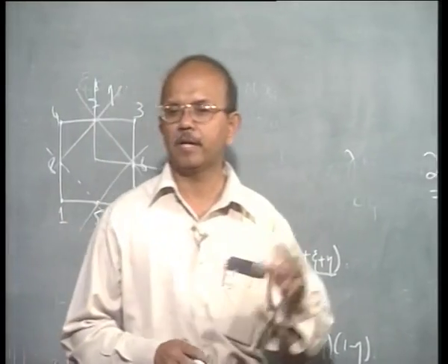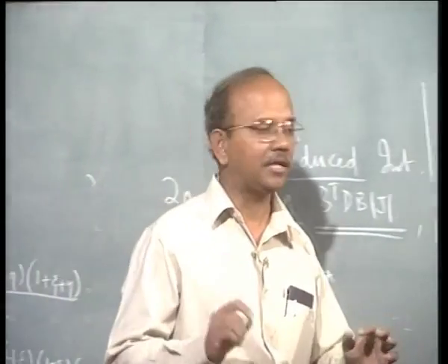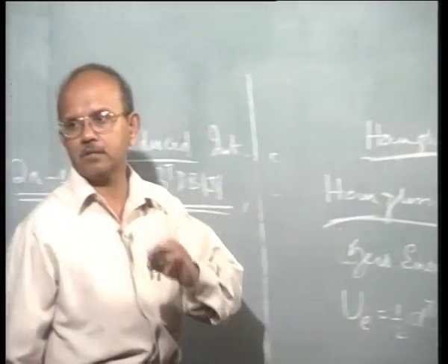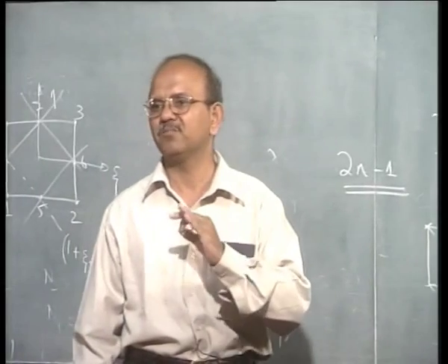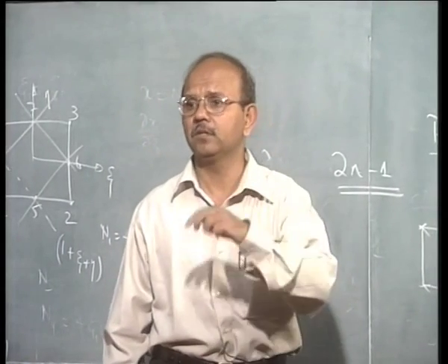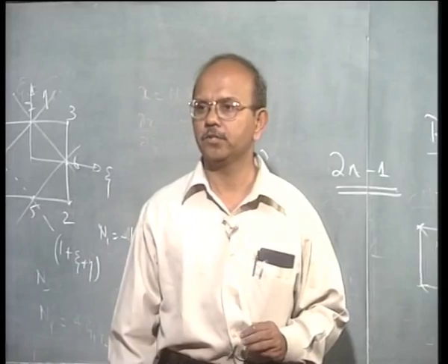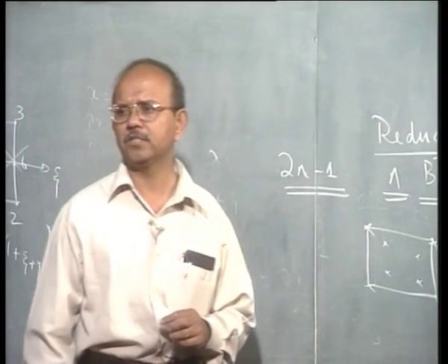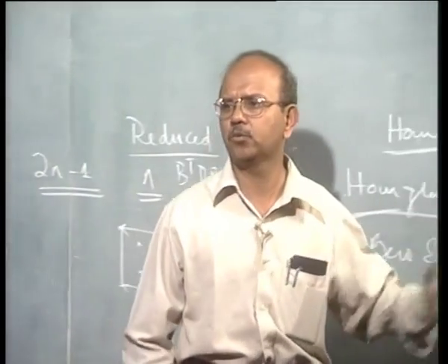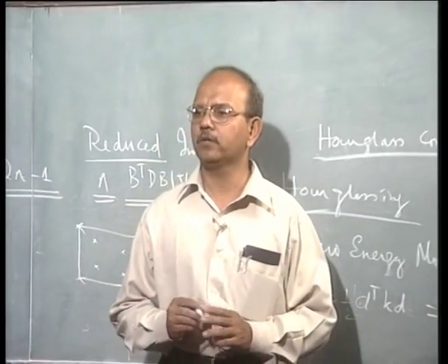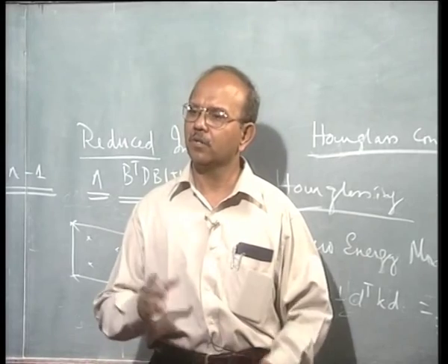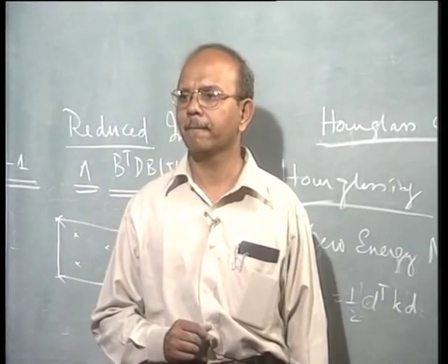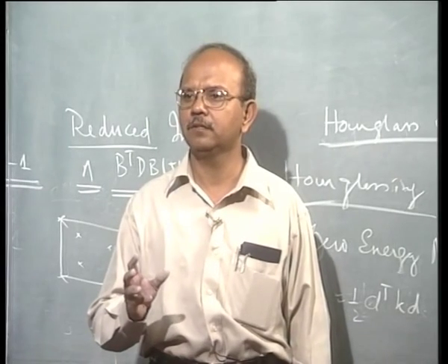We will see that if time permits in the next class, or at least I want to get you to this term, hourglass control. What is hourglass control? They control these hourglassing modes by still using reduced integration with hourglass control. But it doesn't always work because, though theoretically correct, it works only for some nice elements. So one of the things that is recommended is to use reduced integration, but take more elements. That will to a certain extent sort out the problem.